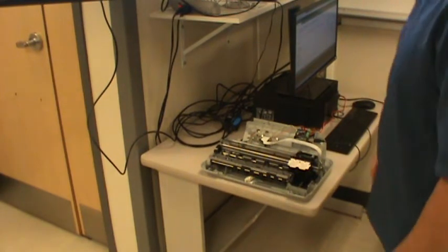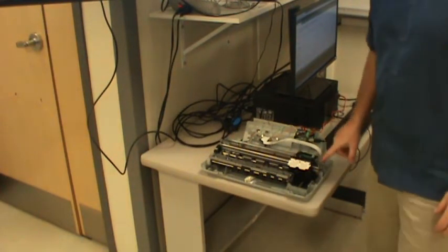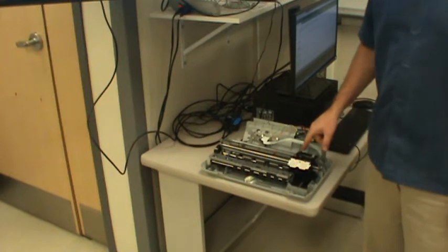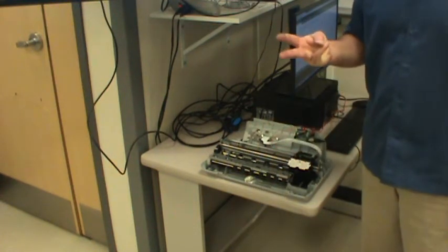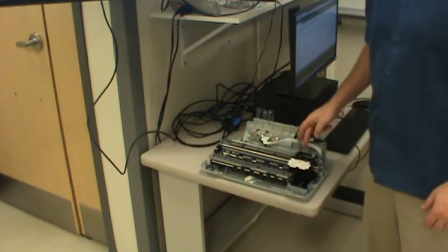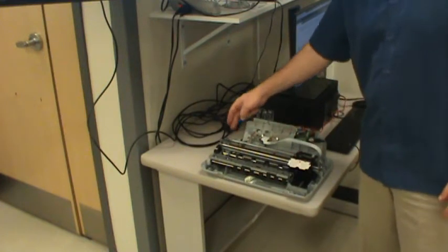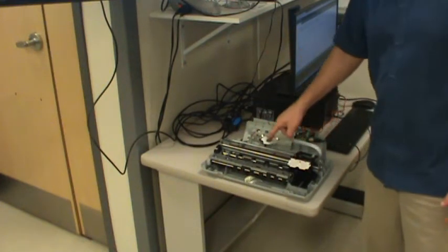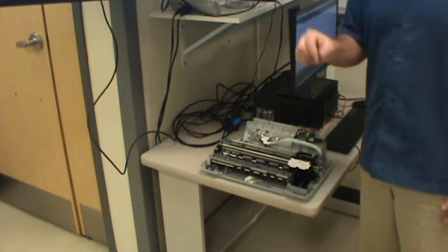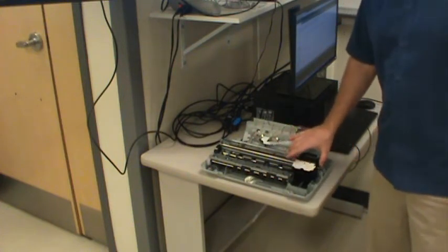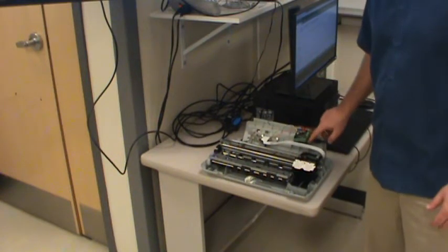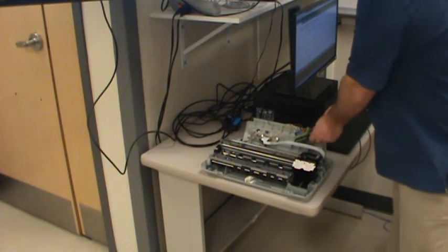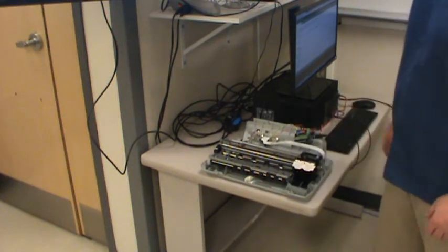I've got it set so that it initially moves over from the edge, and then it takes whatever profile I choose. I've got 3 profiles I've generated, and I'll show you how I did that. It takes one of those profiles, which is just a series of points versus time, and commands different positions. It chooses a different set point for the PID loop. Once it's done, it comes back and stops. So if I reset this, you'll see it move. That way we can see it on camera.